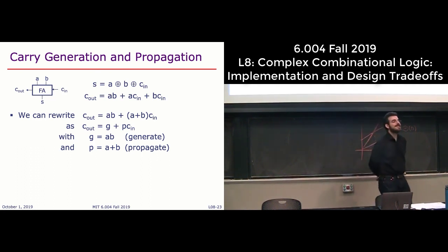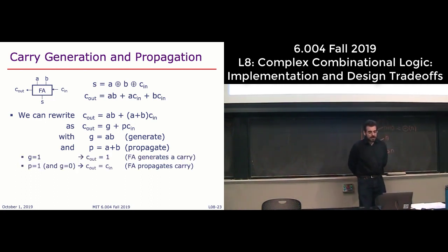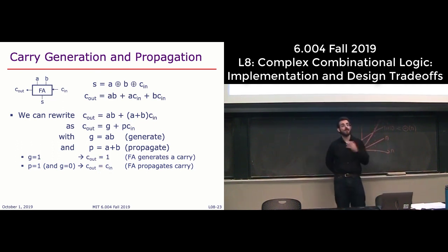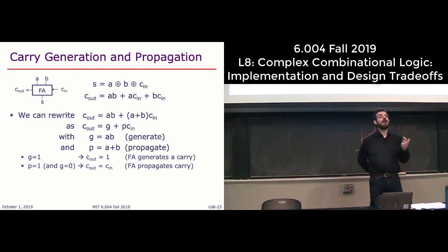Those names are kind of weird when you look at them, but they're very intuitive. Why? Well, if G is 1, then the carry out is 1 regardless of what the carry in is. So we say that the full adder generates a carry.